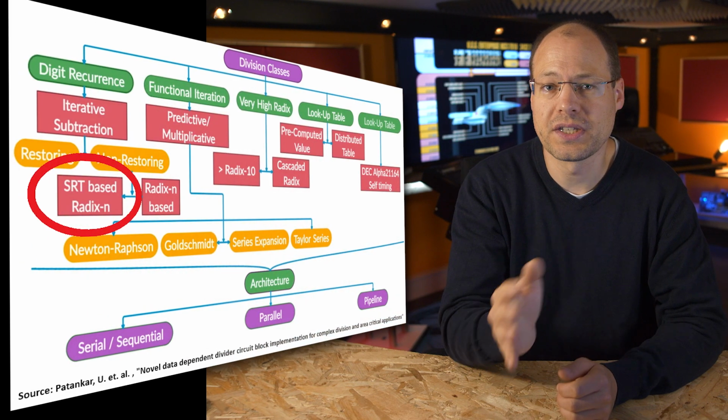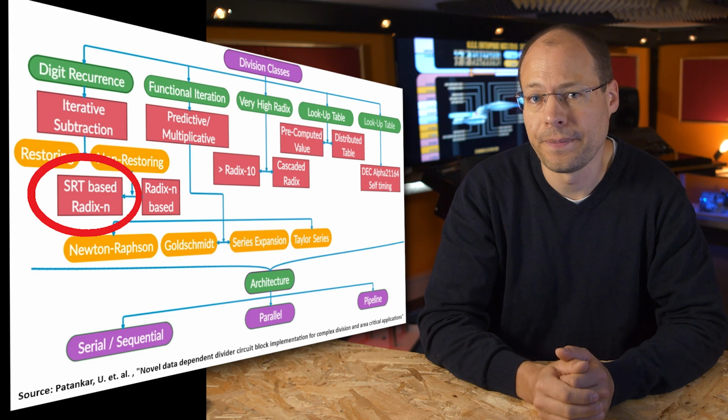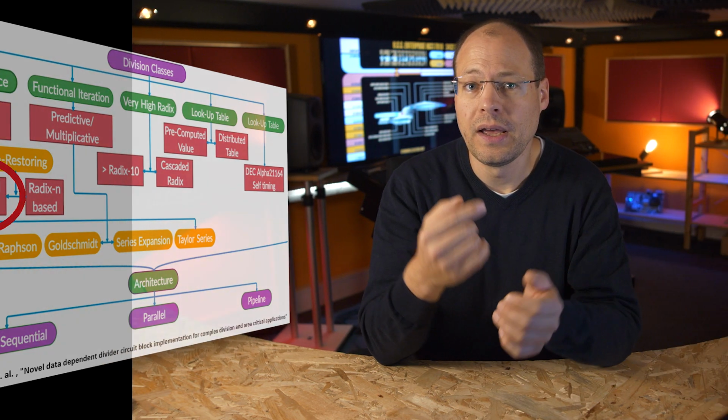Here we can use the so-called radix 2 division, which is carried out in a separate process. The state machine of the compression remains in the division state until the busy flag of the division process changes to 0. This may take a little longer, but we still remain well below the 20.8 microseconds. Finally, we need a low-pass filter, which is a simple filter that determines the rate of changes per time with a single coefficient alpha. This coefficient depends on whether we are in attack or release mode.